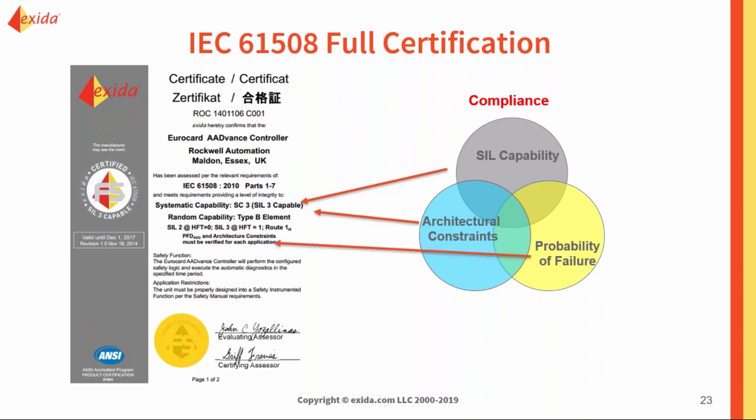And then finally, depending on if it's a device or an element or if it's a complete little loop or not, you might be able to give the PFD average, but chances are it's just going to give you the things you need for the end users to calculate the PFD average. Remember, there's a lot of variables that the manufacturers don't necessarily control. So a lot of the times they give you the failure rates on the back of the certificate, and you can calculate that PFD average on your own.